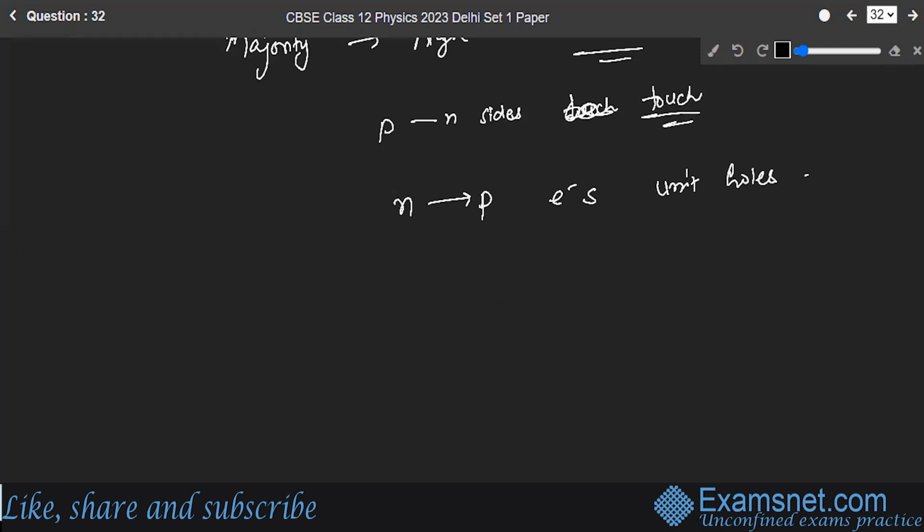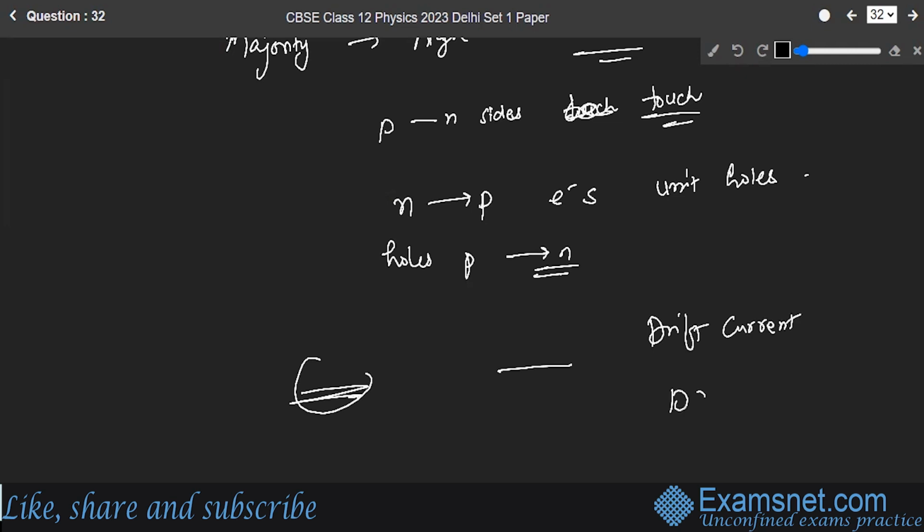Similar to how electrons and holes merge at the junction, holes move from P to the N side. A depletion region is created as a result of the near junction area becoming depleted of the carriers and becoming charged. This is the diffusion current. The charge creates an electric field in the depletion region. At the depletion area, the electric field causes a flow of minority carriers. This created current is known as the drift current, and this is referred to as drift.